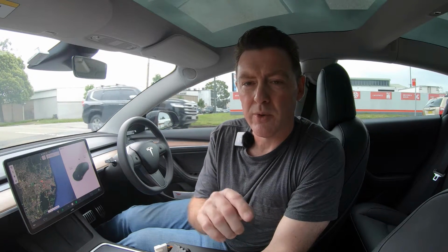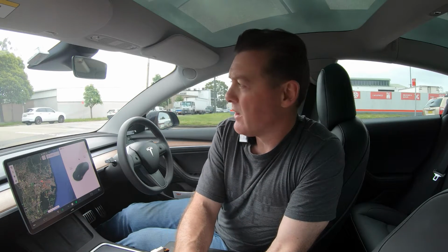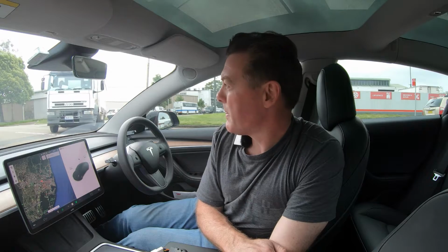So with the sequence of data, the light bulb being on was a 1 in the CAN high, but in the CAN low, think of it as the light globe off is a 1. And then what the electronics does at the other end is it looks at those 2 signals, compares them, and looks for changes. It's constantly checking one against the other and looking for consistency and accuracy in that data. So that's there as a backup and to make the system a bit more reliable, to stop interference from other cabling in the car and other systems in the car.